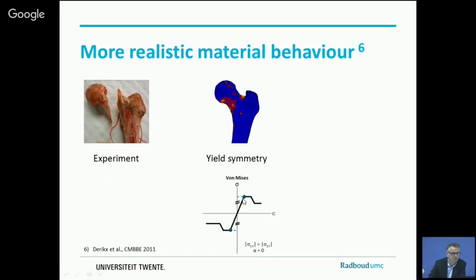So this is linear up to a certain level. If you pass the yield stress, the material will basically plastically deform. So you don't need extra stress, but it will elongate. And if you pass a certain threshold, it even becomes weaker in its resistance to elongation. So here, beyond this point, it's yielding.